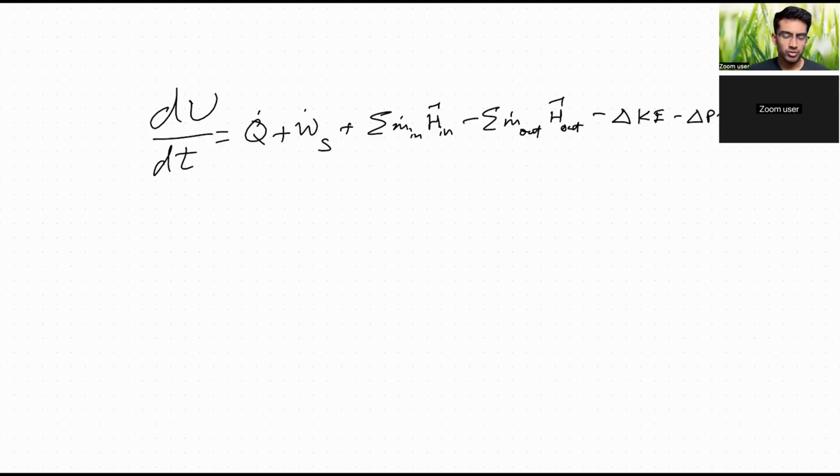Now, you might recall from the previous video that the kinetic energy and potential energy terms were removed, which is pretty typical when we do chemical energy balances, right? There is no real change in kinetic energy or potential energy when we go through a reactor. We're really just curious about what the energy requirements of the reactor are, or how much energy it is releasing. So these things are more important than the kinetic energy or potential energy, so we just ignore them.